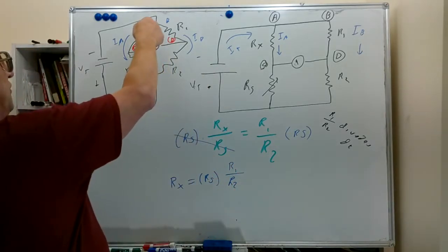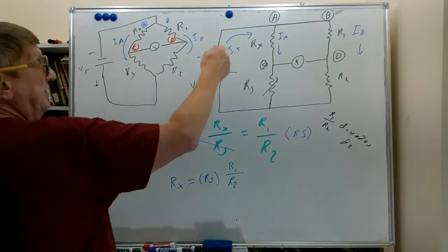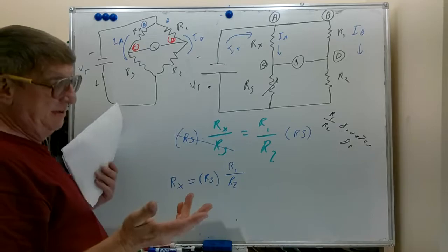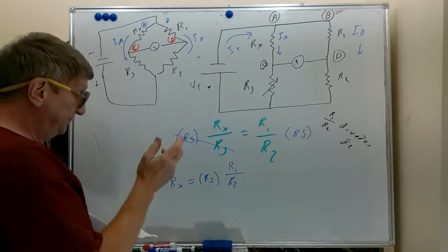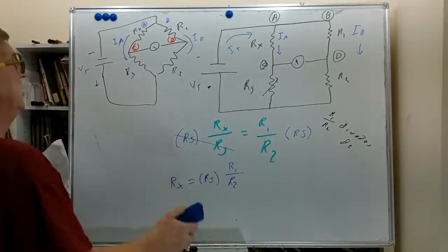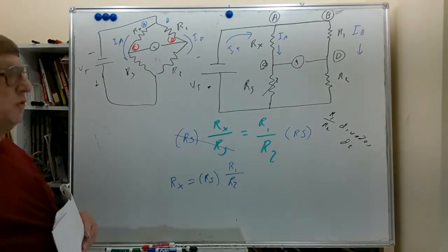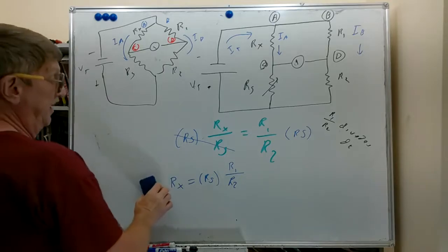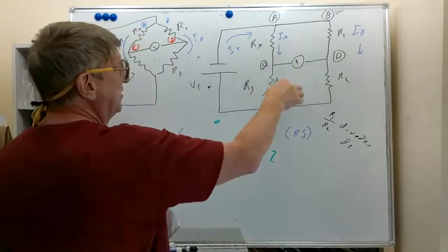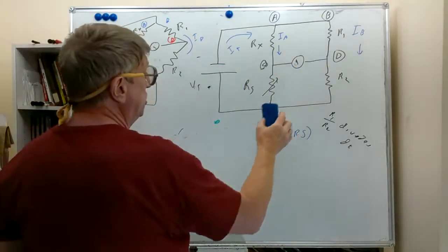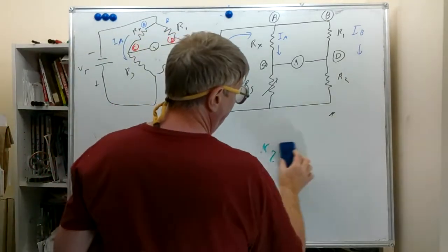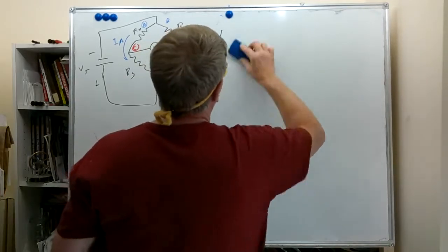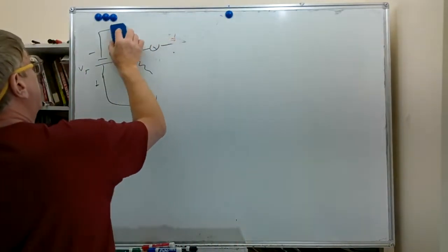And this over here on the left side is the same as branch A, and this on the right side is in fact branch B. You just often see it drawn that way, is the only reason I'm showing you that. But these are identical circuits, and it depends on balancing these ratios to get a null or a zero on the meter, and then you can read off the known values and calculate the unknown.